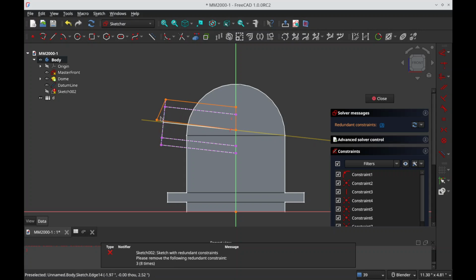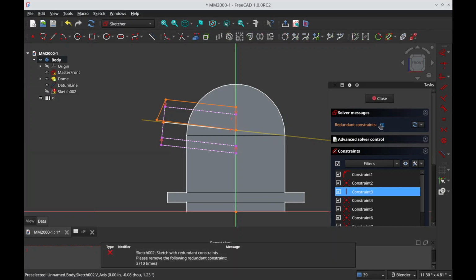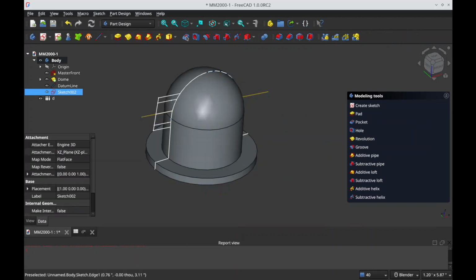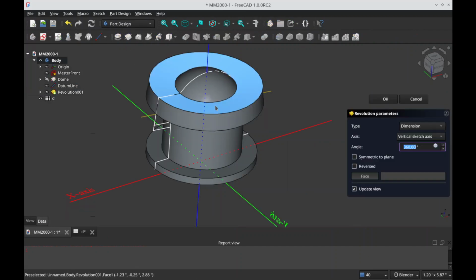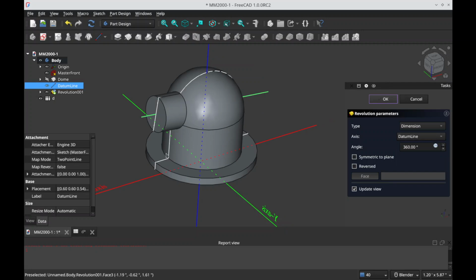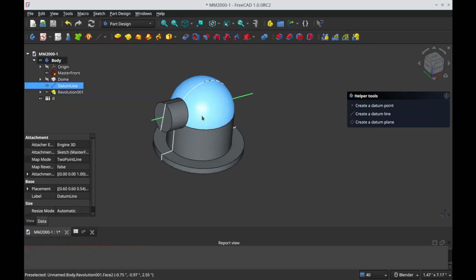Pull that in. Add a center point there. This one also didn't have a center point, so this point we can actually automatically do symmetric. Let's remove the redundant constraints and another redundant, and then finally make that coincident there. Good. Escape. Got that sketch selected. Let's revolve, and instead of doing that, we are going to select our reference as this line here. Voila, we have our master sketch front filled out, and all that remains is the two flanges.